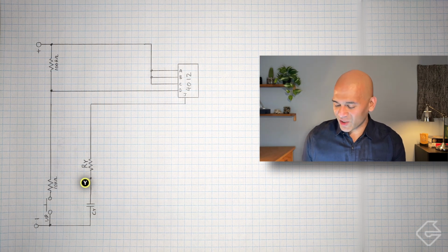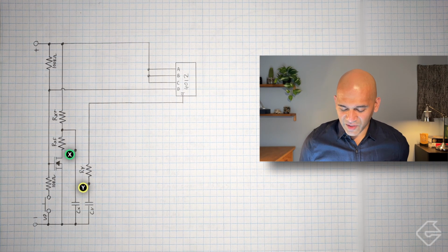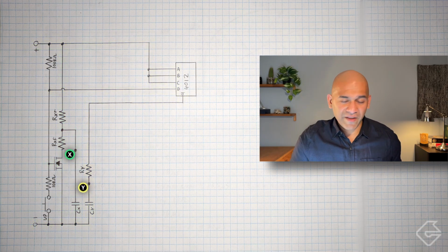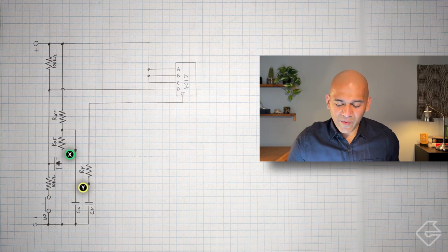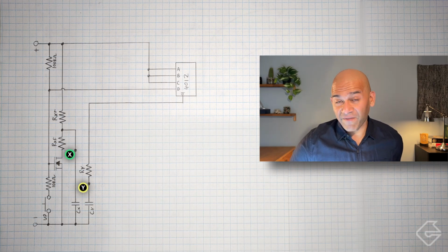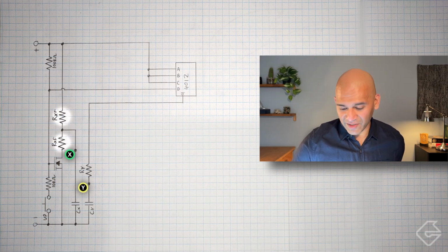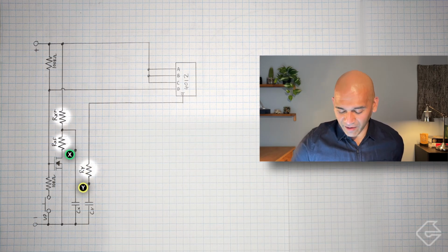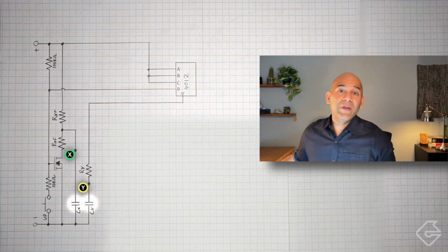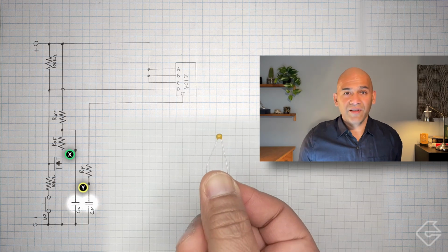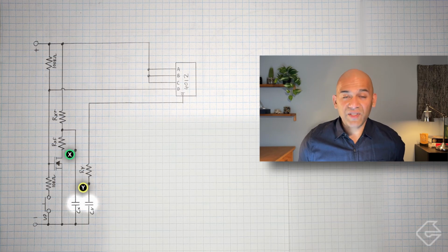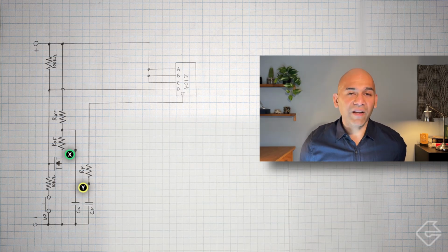Let's put it all together into our new circuit. So here we have the circuit with the X arrangement and also the Y arrangement. So this configuration will work for us. Now, all we need to do, our next step, is to figure out what the values of RXF, RXR, and RY are. We know what the values of CX and CY are. Well, it's not that we know them, I decided to use this. This is our 0.1 microfarad capacitor, I got a couple of these, and I'd like to use these for Cx and Cy. So all that remains to do is figure out the values of those.